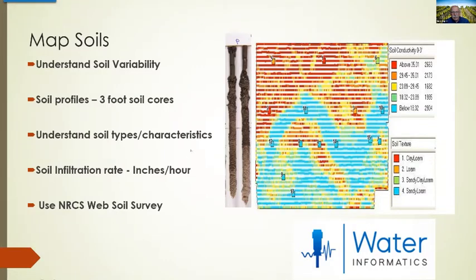So you can see in this core sample, it's probably a little heavier loam up on top. We get a little layer right here about 6-8 inches down. It's sandy, goes back to a loam, probably down all the way to 1.5 feet. And then we get back into sand, and that's a pretty sandy soil right there at the last part of that soil core.